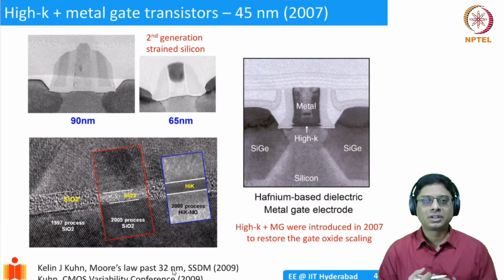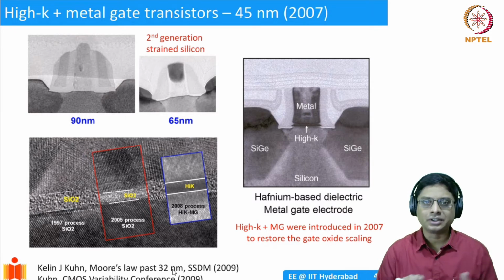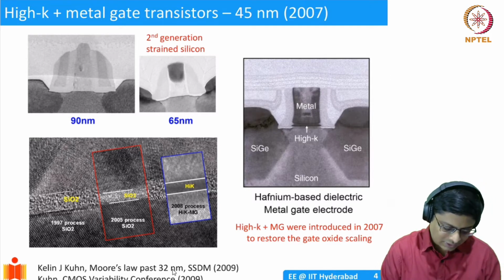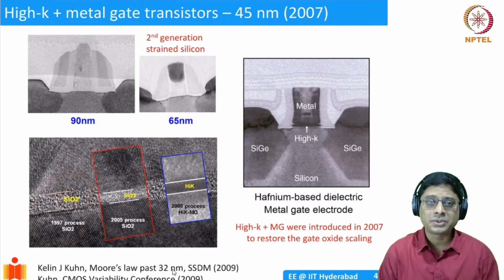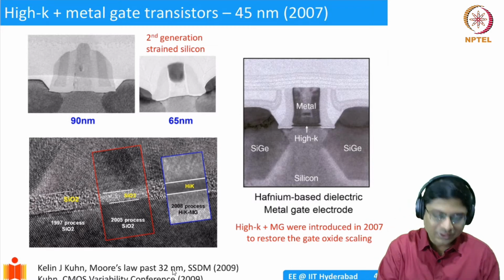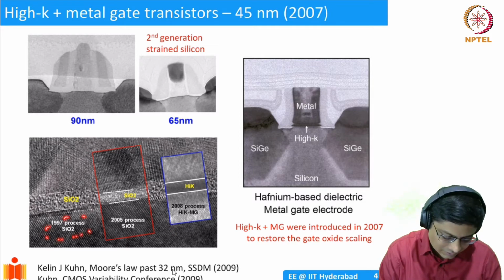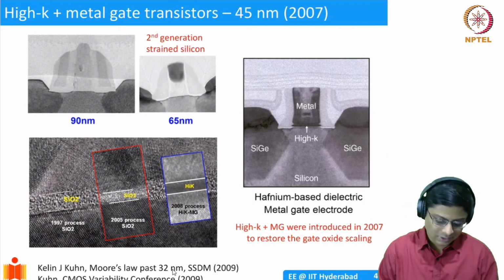And one of the ways to overcome it was that we have to introduce a high K metal gate, or rather high K dielectric. Okay, so this is what was done in 2007. So roughly 13 years back. So this is basically in 1997. The silicon dioxide is substantially thick, and this is what is known as a TEM picture, transmission electron microscope, wherein you are shining electrons into the lattice and then seeing the transmission. And what you see here, the regular structure is all silicon, and this is silicon dioxide, which is amorphous, and then polysilicon on the top. Okay, this is in 1997.